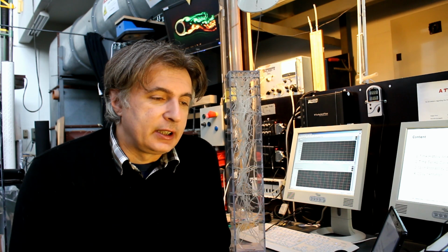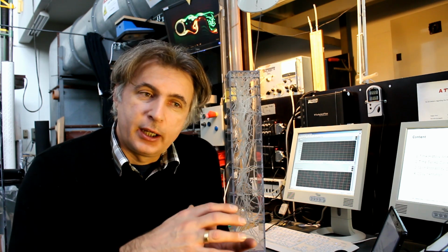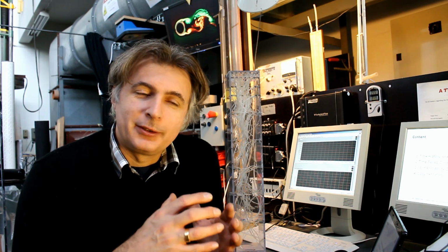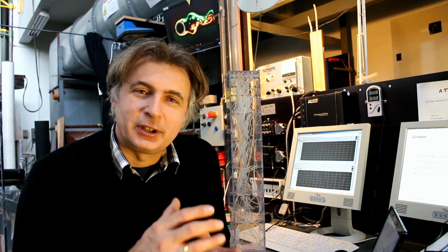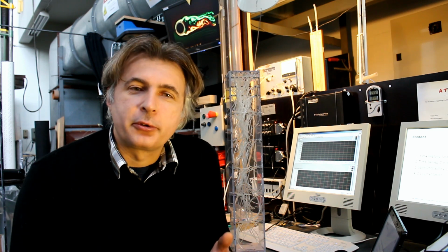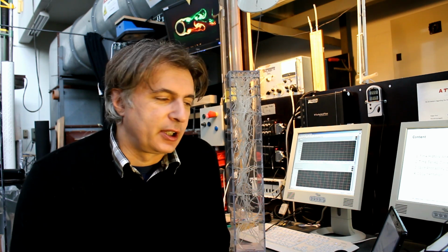In one case it can be the resistance of a structure, and on the other side it can be the load of the structure. If these two elements play with each other and are combined, the resulting joint probability is used to calculate the overall exceeding of a specific load level.